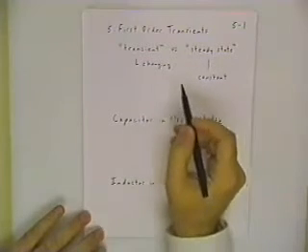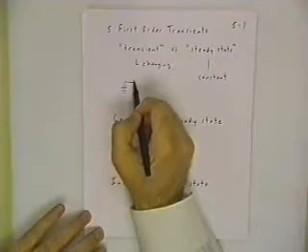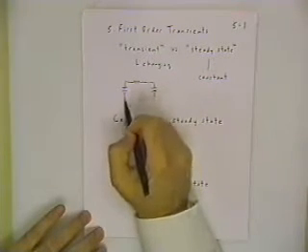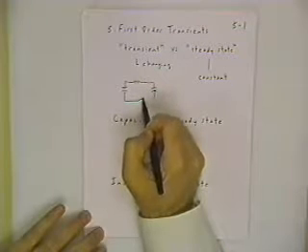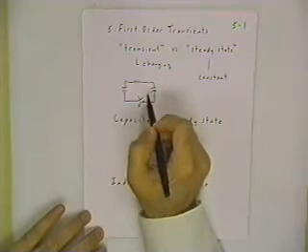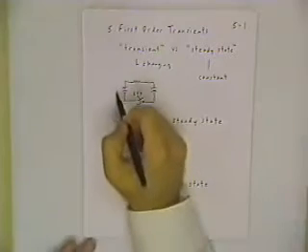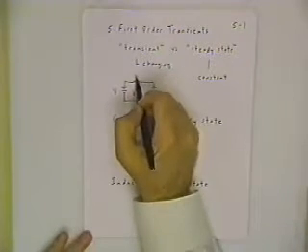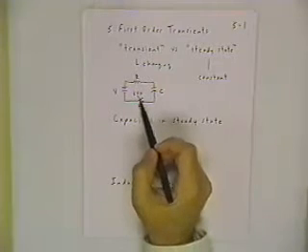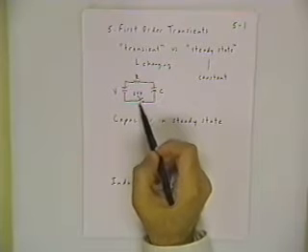So if you think back to that capacitor charging problem that I sketched before with the resistor and a capacitor, in these transient problems it's very common to have a switch in the circuit, and that switch will sometimes be labeled with a particular time that it's going to either open or close. If this is a voltage V and this is a resistor R and capacitor C, what we can discuss just verbally is what will happen when the switch closes.